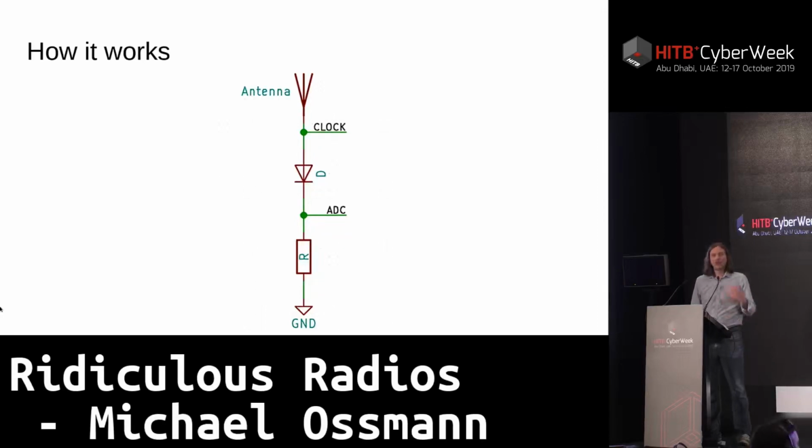So one of the features of this microcontroller is that it has 2 or 3 fairly flexible clock generators inside of it, and they can operate at frequencies up to a few hundred megahertz. And it happens to have a way to produce an external clock output from one of those internal clock generators.